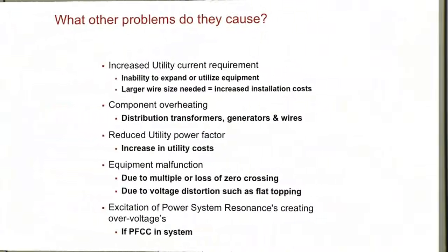More impedance, right? So the higher we have impedance, the better we look or get better voltage ratios out of it. And we'll see where that comes into play with IEEE 519. But you can see also what happened. My current distortion actually went down compared to this slide of 37%. But my voltage distortion went up because I have less impedance in my system now. Okay, that's also with your cabling that you put in your system as well.